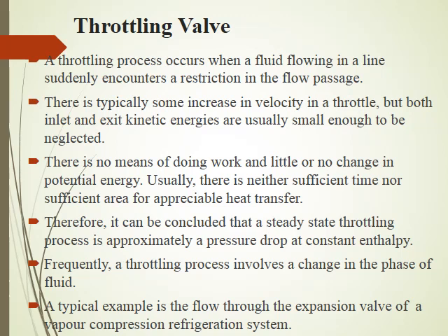So the conservation of energy equation for the single stream steady flow devices basically reduces to Hi is equal to He, which means the process is isenthalpic. So we can say the throttling process is an isenthalpic process, which means the pressure drop is taking place at constant enthalpy.